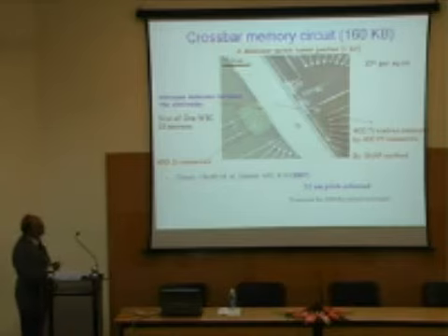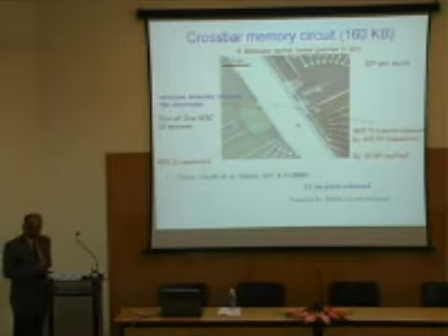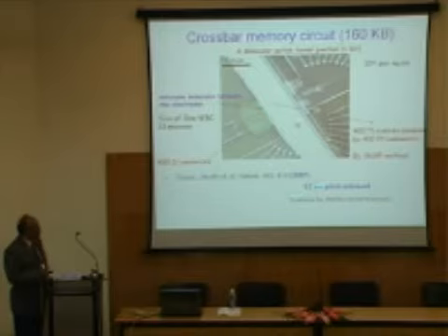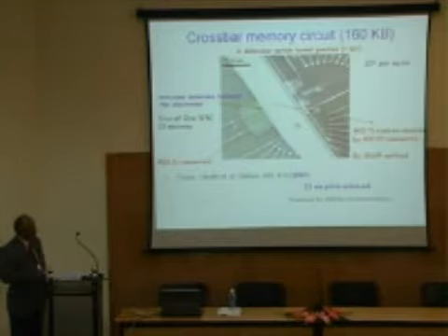And this is one of these, which is 1 bit, and they have been able to make a 160 kilobit device. And in these devices, the distance between the wires is 33 nanometers. By conventional lithography, it is predicted that you will achieve this in 2020. So, this is a great jump in technology by the solution or molecular method. Okay.